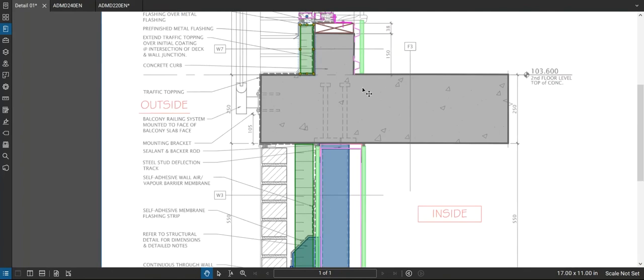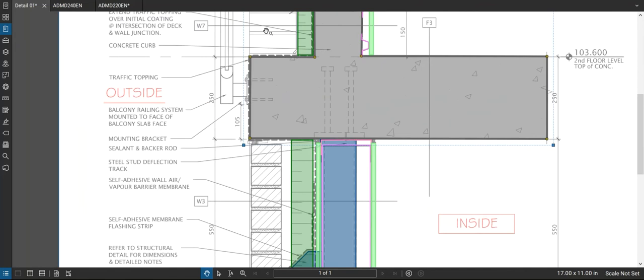So now we can start to see that, oh yeah, we've got a pretty big problem here. A big thermal bridging problem. There's no insulation through the concrete right there. It's been broken. And so what would happen here? Okay, so if it was, say, minus 25 outside, and it's plus, I don't know, 22 on the inside right here.